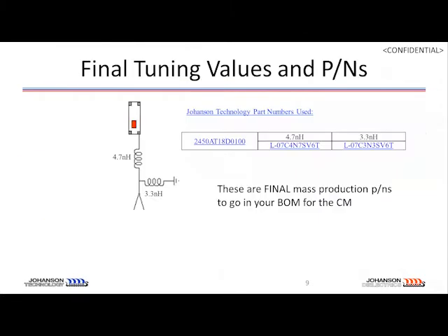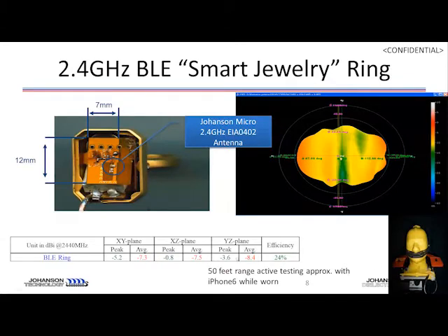values. How that works is we will measure right at the feet of the antenna, before the slots available that we will recommend. Usually it's a shunt, series, shunt fashion of available slots to tune, and we will find the values, measure this in one of our two anechoic chambers, and give you the actual measured antenna efficiency of the assembled prototype. So this is pretty close to reality in application.